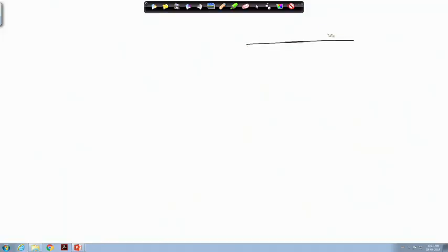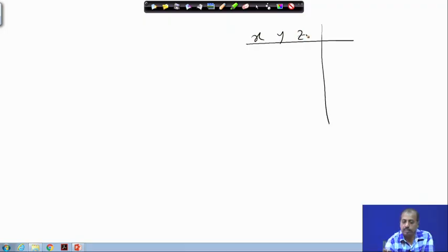So, what I mean is that if I have a 3-variable function, say with the variables x, y and z, and I need to realize it in terms of a 2-to-1 multiplexer, then I am doing a partitioning where these are all the combinations that I have.